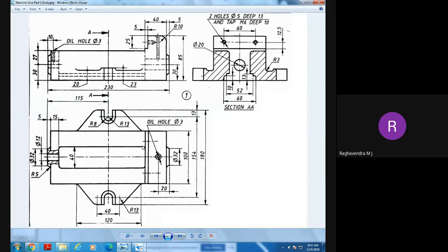Look, we need to cut here. Are you able to see this here? This is a cutout which is made looking from the top. But in the side view, looking from here, this is the view we are going to get. So this cutout width is 60, and from here to here it is 52. Once again, this height is 10, and this side is 13. And up to 30 plus 27, up to 57. We need to cut this shape, removing the material in this shape.